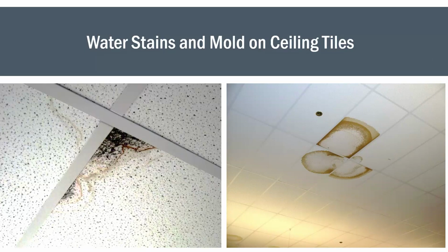That's something you document. You can pop your head above the ceiling tile and take a look around, see what you see. You can document that. Are there sprinkler pipes up there? Do you see active drips? Is there daylight coming from the roof deck above that area? Maybe it's a roof leak. Other things could be HVAC ducting, condensation drip pans that are located above the ceiling. So a lot of factors. Really, you're documenting, you're taking pictures, you're looking around.